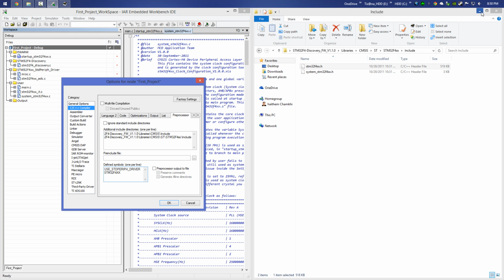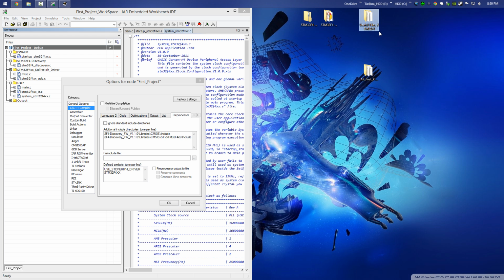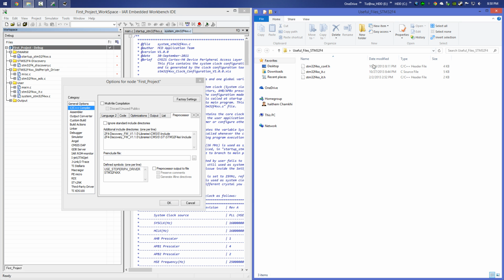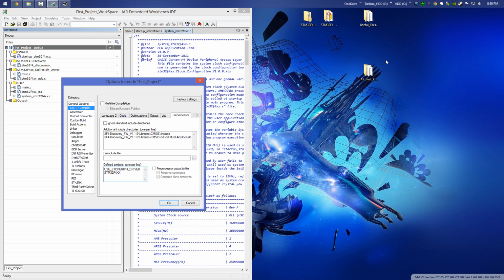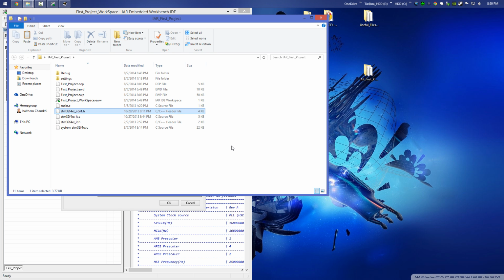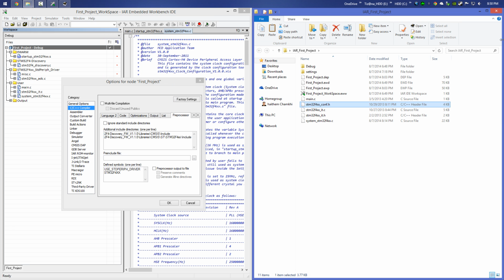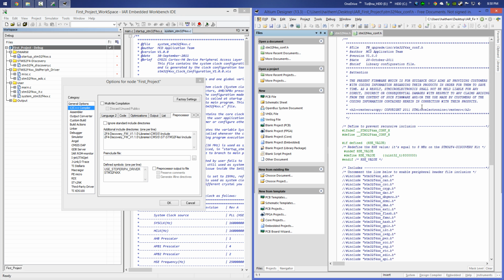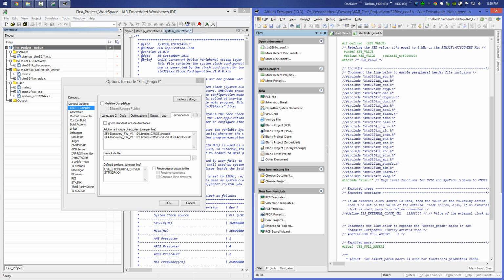It's quite simple. We're gonna find it under the utility file. We open the utility file and we have the last utility file, the configuration. We copy and paste it under our project directory, and we open this configuration header file. So here we have all the driver header files. They are written like a comment, so this is not activated, only the miscellaneous, the important one.